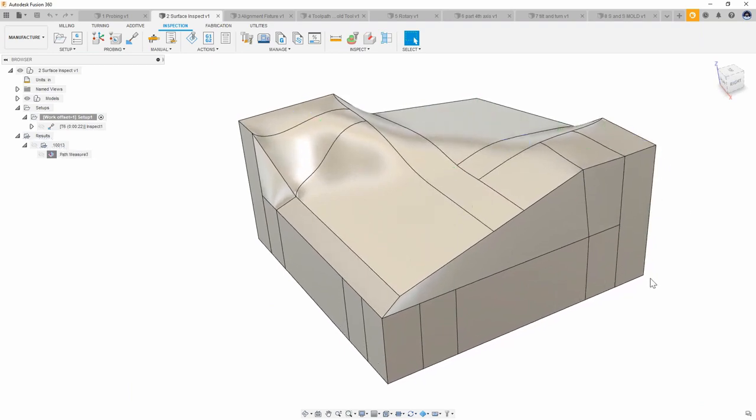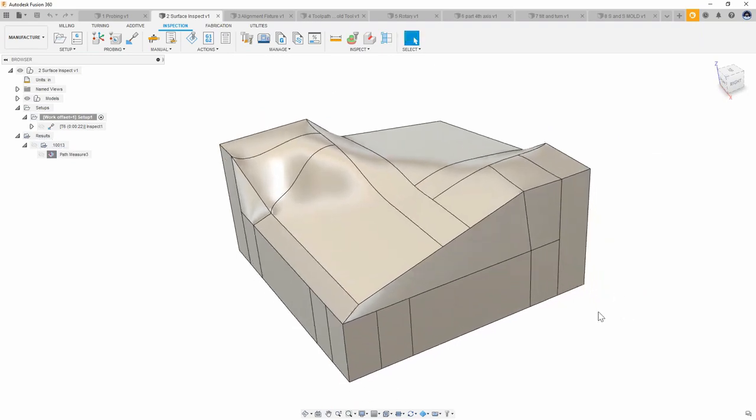Now, another thing that's very common is, instead of doing that on the machine, if I didn't have that probing, or I want to manually check this on something a little bit more dedicated to measurement, like a CMM, I might take this component off of my machine. And what I might do is bring it into that room, have it acclimate to the temperature, and take some measurements on it. And then if I do find that there is some sort of issue where it can be repaired or fixed, I would have to take that component and bring it back over to the CNC machine.